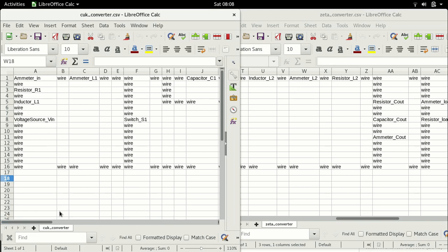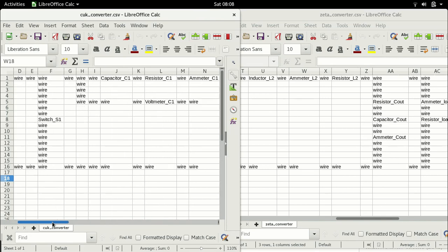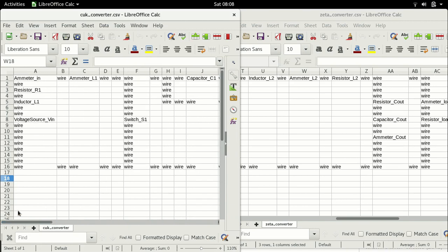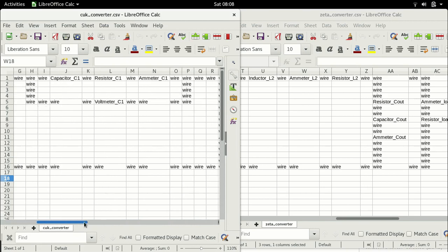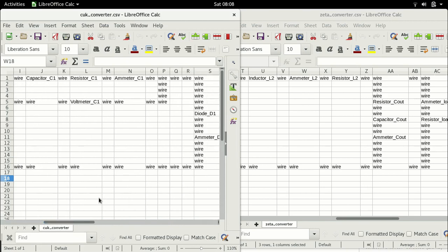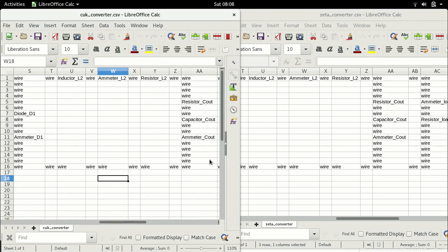So with this little discussion, the main question here, the biggest difference, is the size of the capacitor and the current flowing through this capacitor. In the case of a CUK converter, it is this capacitor which is connecting two parts of the circuit. Right? The capacitor receives current from the input voltage source and it supplies power to the output voltage.